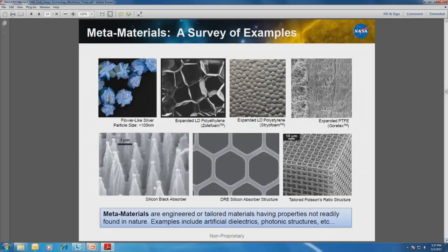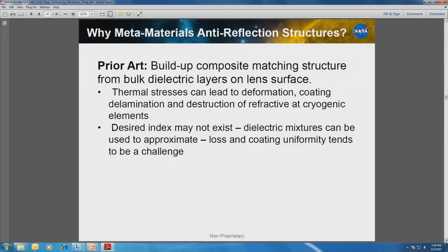And some of the various techniques: these are made by chemical etching, essentially. This is made by laser-assisted etching. This is done by DRIE, and this is by similar micromachining processes. Some of these, like these nanoparticles, are made by essentially just controlling the chemistry in a way to generate particles of a certain size. Next slide, please.